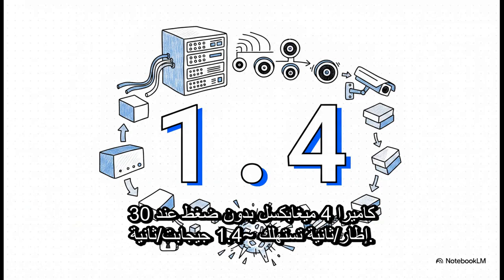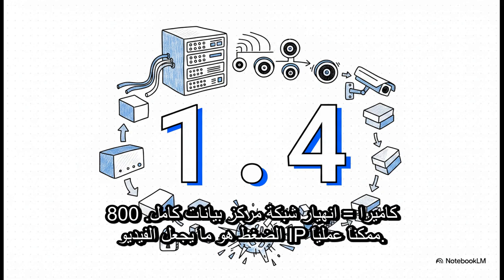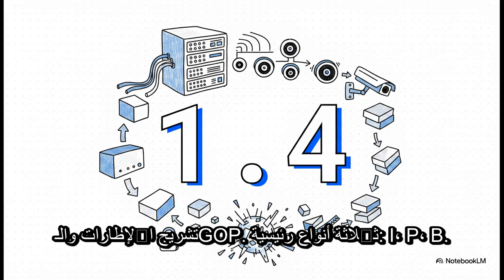Every CCTV system records video, right? But without compression, a single, raw, 4-megapixel camera streaming at 30 frames per second consumes roughly 1.4 gigabytes per second. Just think about that. If you multiply that by a standard deployment of, say, 800 cameras, you would instantly crash an entire data center network. Compression is what actually makes IP video physically possible.